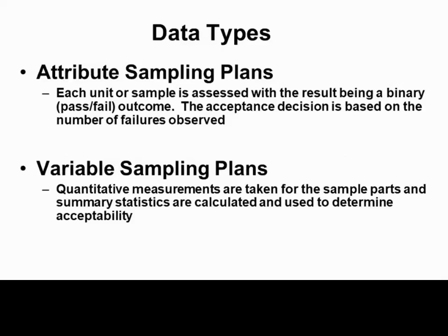Whereas variable type data is more useful to us because it's not just pass or fail. We know by how much a failure is or by how much a passing is. We get a quantitative assessment of that characteristic. And so one of the advantages of variable sampling plans that we'll see is that the sample sizes are going to be more reasonable.